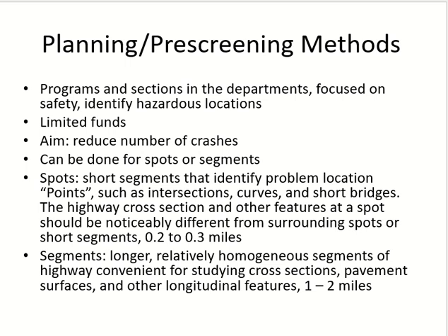Maybe the department is focusing on signals. Then sites which have signals automatically become part of your analysis. So one thing is the priority of the department. Then the hazardous locations, the locations which have more accidents, obviously they should be there. Why are we doing this? Because the funding, as I already mentioned, and time are limited.